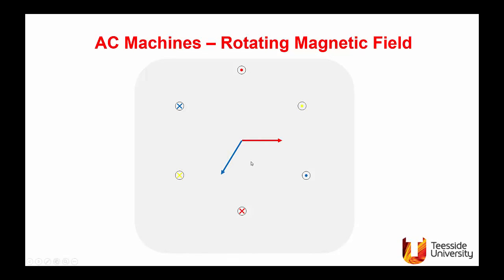But the yellow current increased to 2 amps. So that's the yellow field, twice the length of either blue or red. Add these 3 vectors together, you end up with the resultant component. You can see now that the resultant component has moved. It was at theta equals 0, now it moved clockwise to this position as a result of the changes of the magnitude of the excitation current in the 3 coils. This can be illustrated in the next slide with some animation.